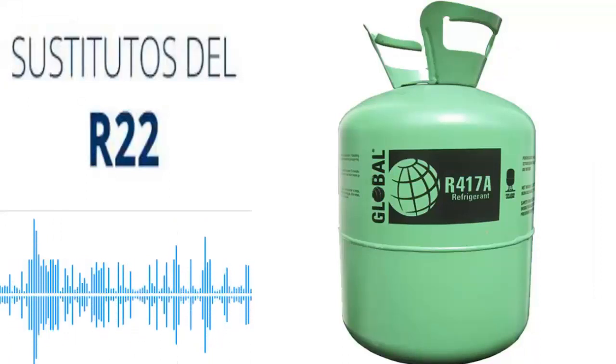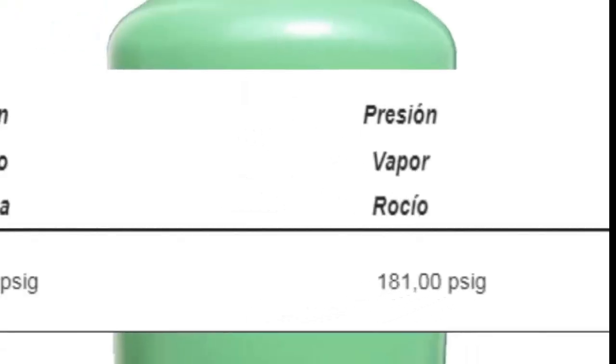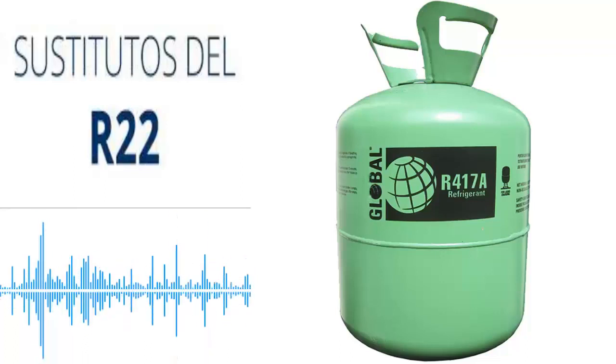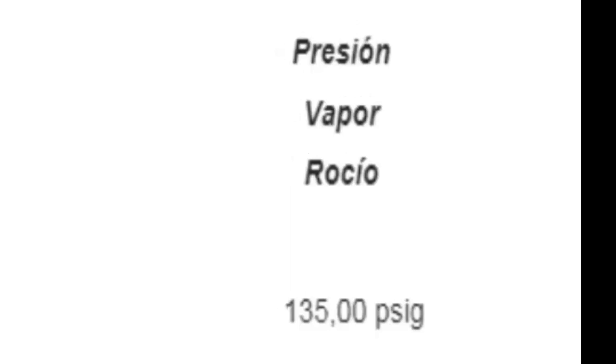When we want to know the high pressure, for an ambient temperature of 30 degrees Celsius, the condensing temperature is usually close to 40, about 10 degrees Celsius above. The pressure gauge, in this case high, will mark about 12.48 bar or its equivalent, 181 psi. When the equipment is off, there is no low or high pressure, everything will depend on the external temperature. If we make the comparison for an environment of 30 degrees Celsius, we will have in both pressure gauges a pressure of 9.31 bar, equivalent to 135 psi.